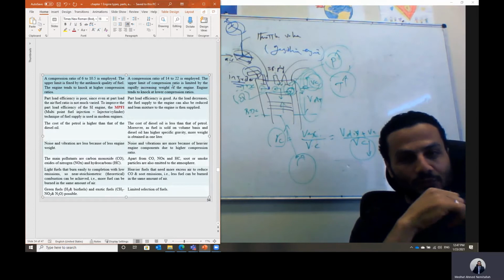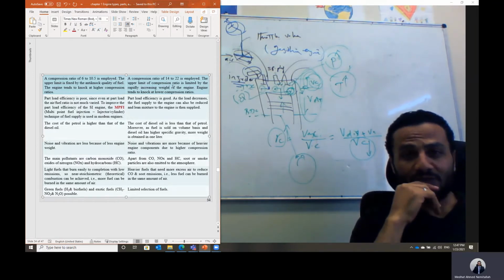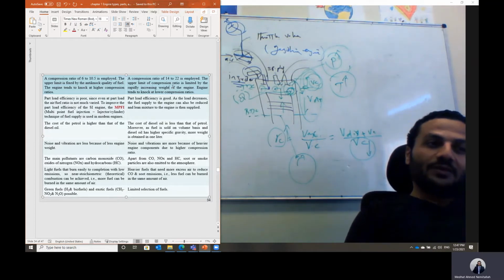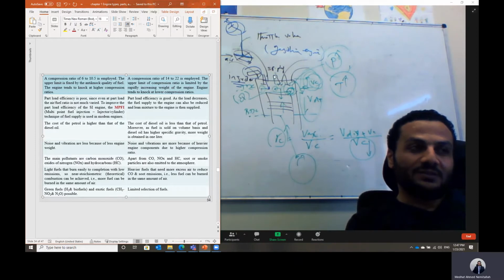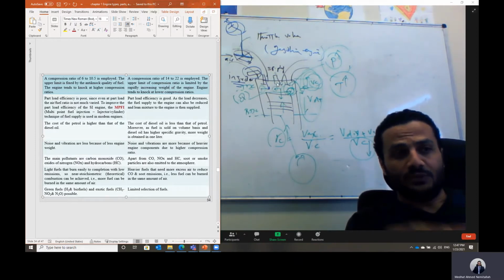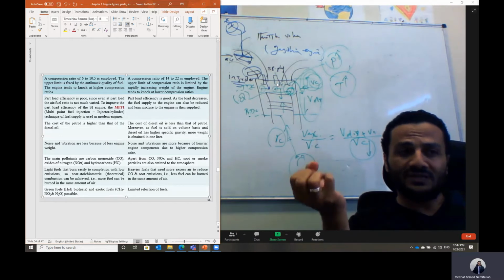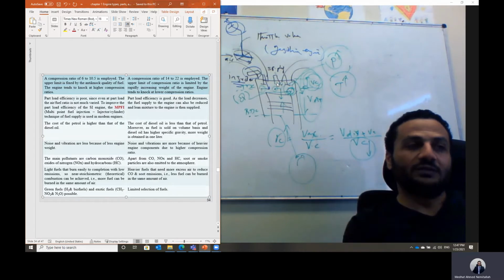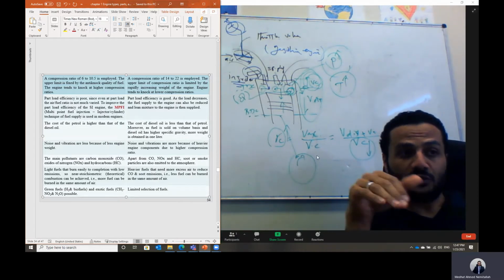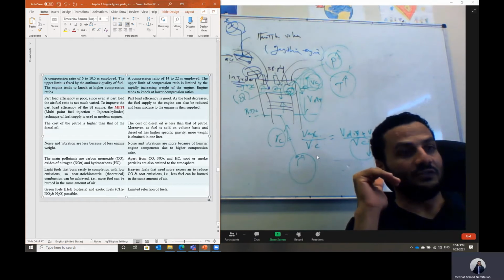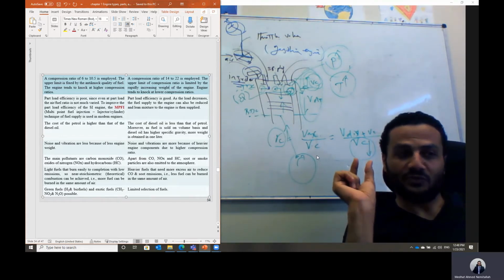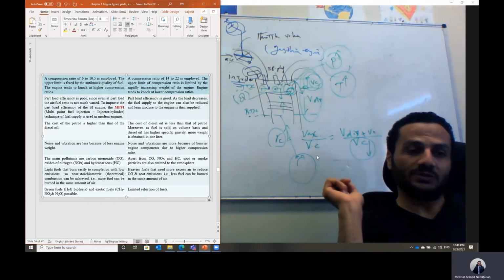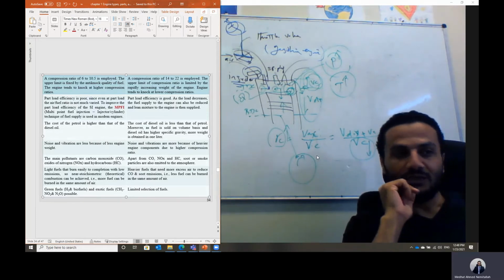are diesel engines not widely used? You will see gasoline engines everywhere, but diesel is limited to heavy duty trucks and things like that. Why? Because the diesel engine depends on injecting the fuel at the end of the compression stroke. Once injected, this fuel needs some time to mix with air and to start the combustion. So it needs some time. If we are working at a higher RPM of the crankshaft, the piston will be moving up and down very fast. So in this case, the time for the combustion will be reduced. That means we have incomplete combustion. So we will have a significant power loss at high engine RPM.